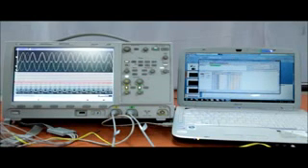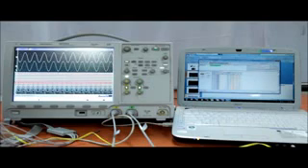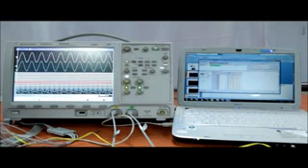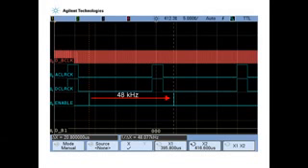We can observe the synchronization signals between the audio codec and the FPGA by switching the signal bank. By zooming into the oscilloscope, observe that the interval between the ADC-DAC enabled pulses is about 20.8 microseconds, which is the reciprocal of 48 kHz. This is a signal that indicates the ADC has captured a pair of left and right channel samples, and the DAC is ready to accept another pair of left and right channel samples.